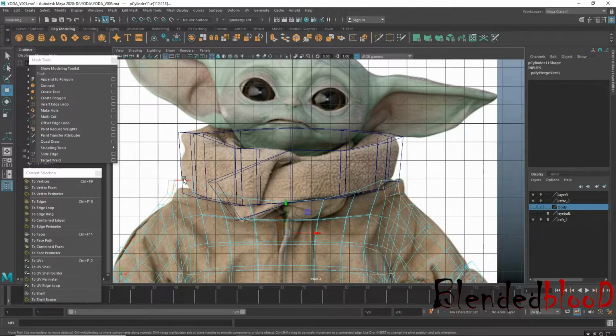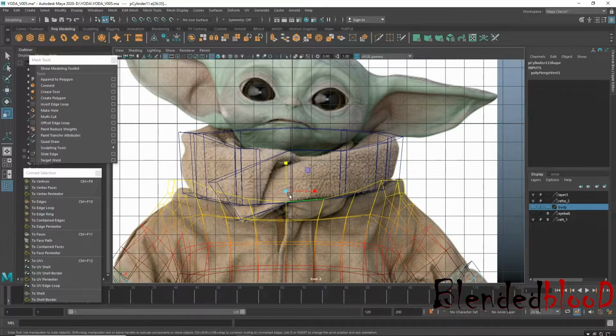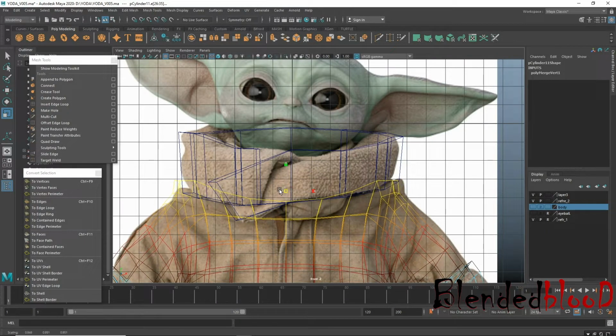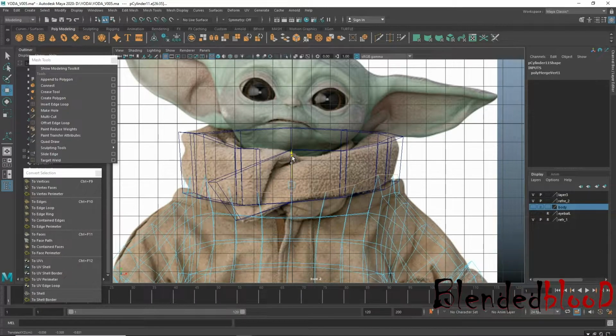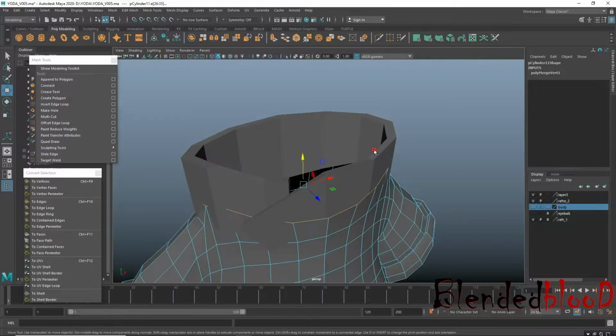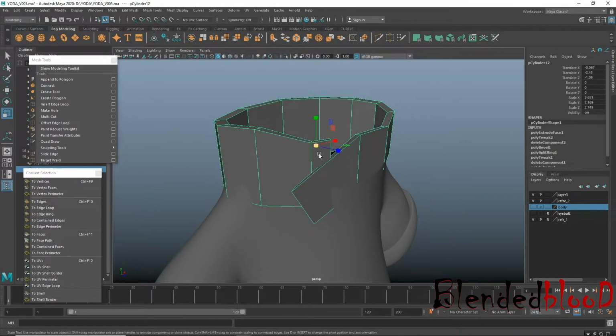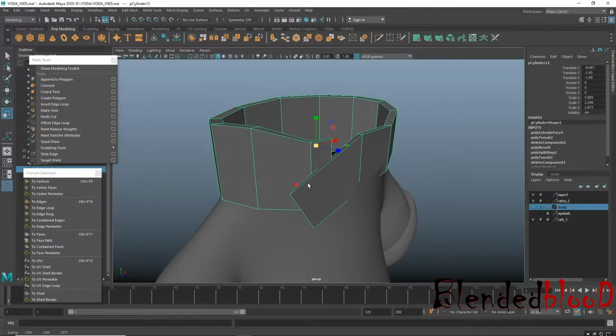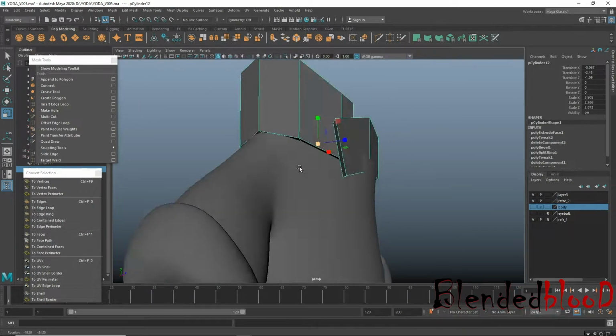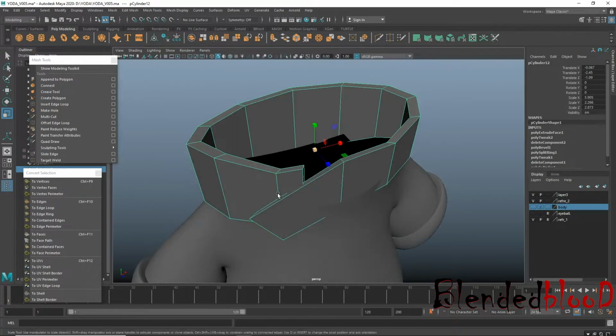Edge, select this area, select B for soft selection, press R, and your cloth starting point should get into his scarf or whatever you said under this area. Hold B and like this. Okay, and this area should be a bit wider like this. You have to manage this manually, definitely.